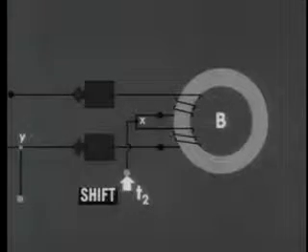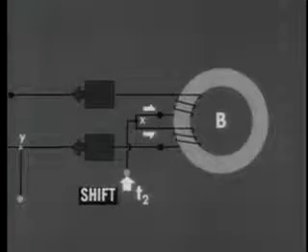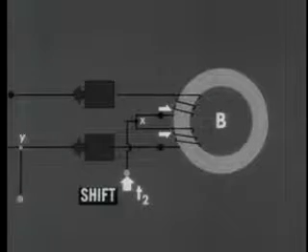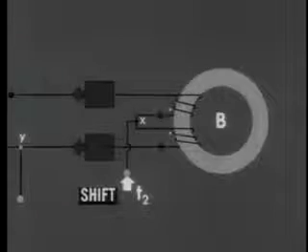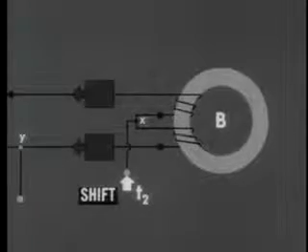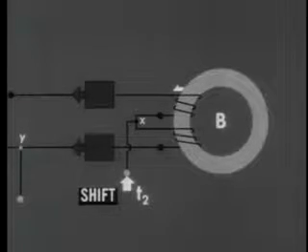As we saw before, this current goes to point X, where it divides, and the branch currents enter the two halves of the split winding. The upper branch current comes out on the non-dot side of its half of the split winding. The lower branch comes out on the dot side of its half of the winding.